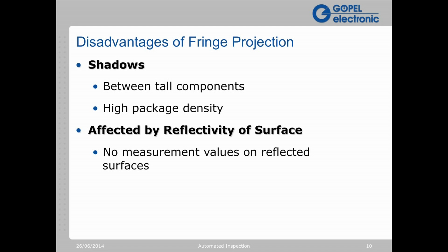High package density can also produce shadowing. Even for relatively small components, if the packaging is very densely packed, there can be shadow effects that eliminate coverage on the board due to shadows on critical areas to be measured.